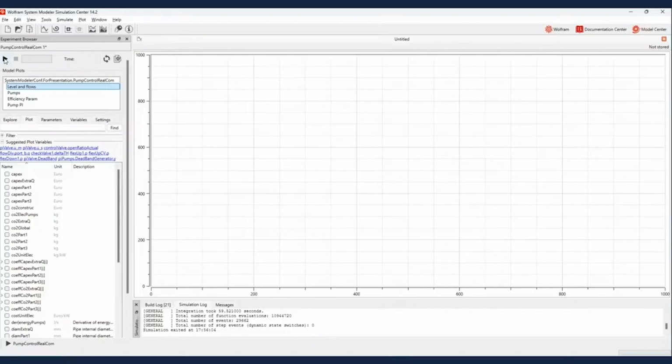So at the interface, in our head library, we use total head in meters, which is kind of pressure, but expressed in meters of water column. It's the level of the water in a transparent tube that would be connected to the pipe.